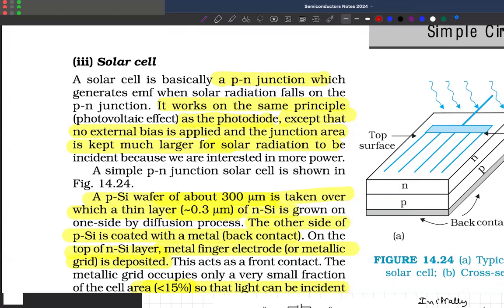These electrons which are going up get collected here. These holes which are going down accumulate here as a positive charge. You may ask me how holes become positive. Practically, holes are not becoming positive. To fill these holes, electrons are given out by this conducting plate.